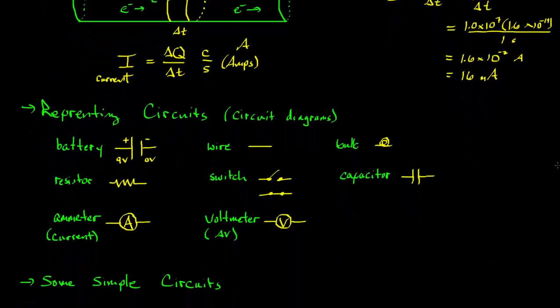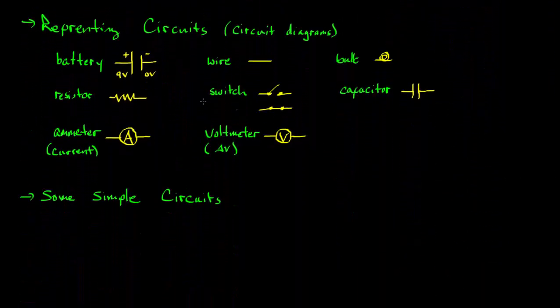All right, so now we can start drawing circuits before we talk about them. These are the symbols that we'll use. For a battery, this is a single cell battery. If you look online, you'll see multiple cell batteries, something like this, like a 2-cell battery. Anyway, we'll just use these. You have a positive side and a negative side. The long side is the positive side, and sometimes you'll have the potential at that side written out. We typically will set the negative side to 0, and then the positive side would be whatever the potential difference is across the battery.